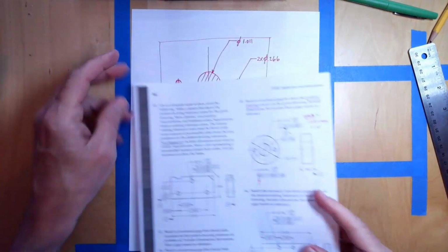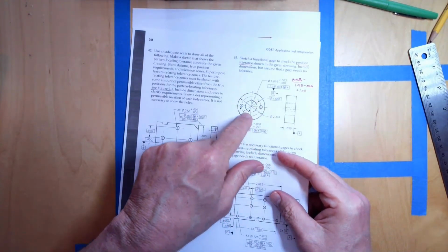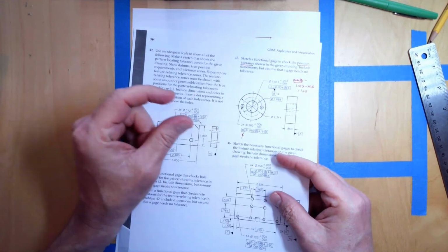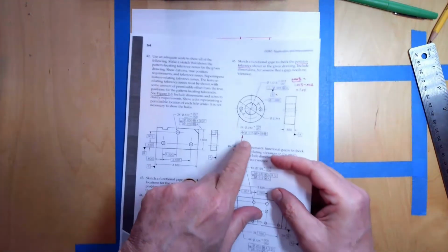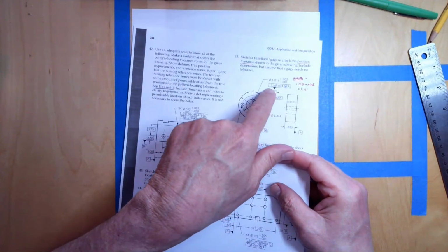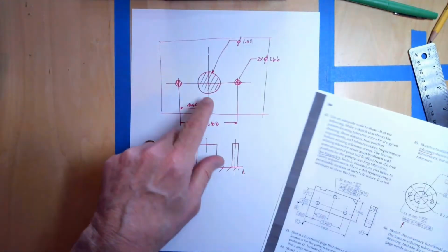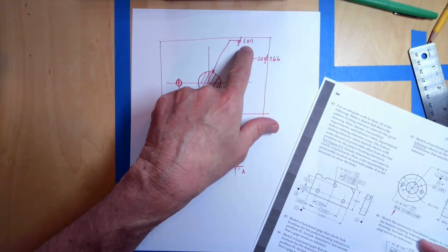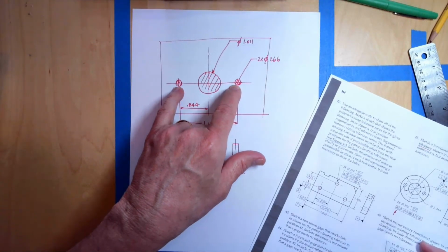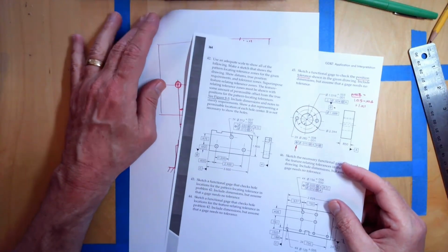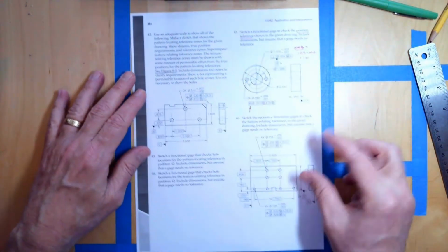With a functional gauge, these pins are designed, they must be smaller than the holes that they're going around. But the size of these pins takes into account the positional tolerance. And in this case, also the perpendicularity tolerance, because we're looking at the maximum material boundary for that and the virtual condition size of those. Okay. So that's problem number 45 then. All right. And the last problem we're going to look at is problem number 46.